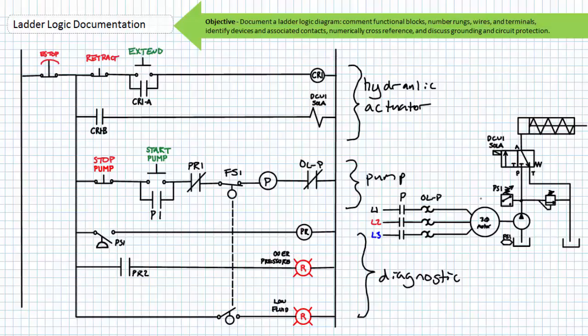Keep in mind, the title of this lecture is Ladder Logic Documentation, and I am not asking you to interpret this particular ladder logic diagram. All we're going to do is to learn how to properly document it. Later lectures on pumping circuits will make use of a derivation of this particular diagram and discuss it in great detail. For starters, we need to number the rungs.